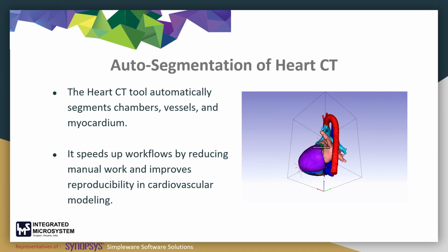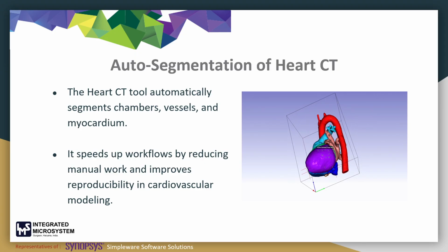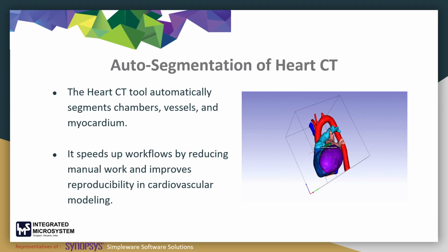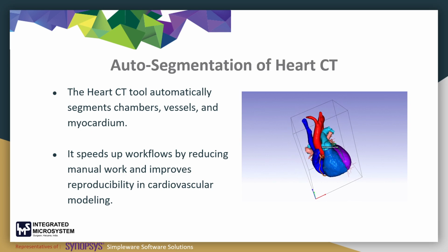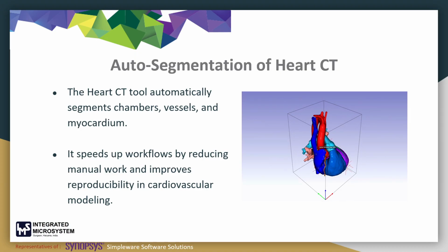Another key advantage is that this automated segmentation is fully editable. Once generated, you can still inspect, adjust, or refine each region using standard Simpleware manual tools. This gives you flexibility to fine-tune areas like walls, valve faces, coronary ostia, or regions with image artifacts without starting from scratch.